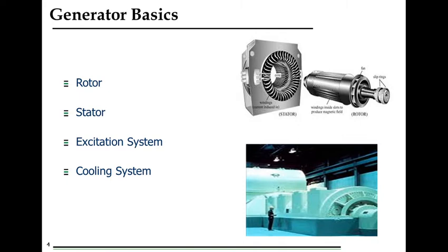Whenever current is flowing in a circuit, it will produce a heating effect. So in a generator, we have stator winding and rotor winding, and both are carrying current. So both will be heating up. We need a system which can cool the heating effect of the current carrying conductors. For that, we have cooling system. Lower capacity generator may simply be air cooled. As we move to higher rating capacities, the air cooling changes; the rotor can be hydrogen cooled, and the stator will be water cooled.